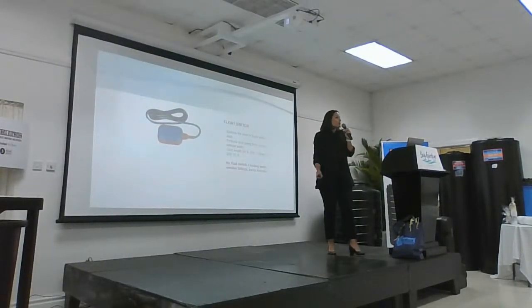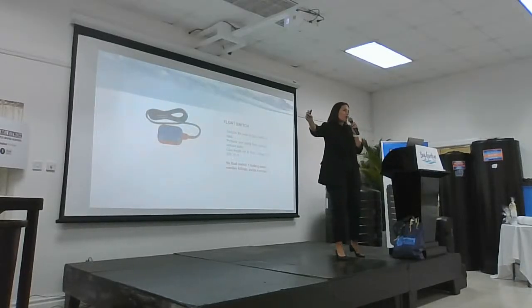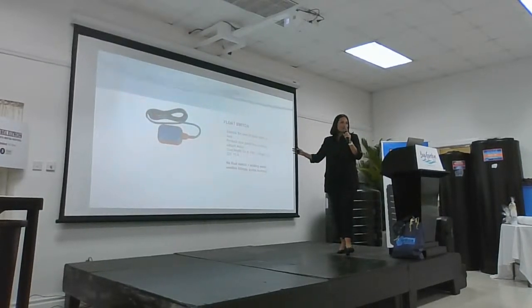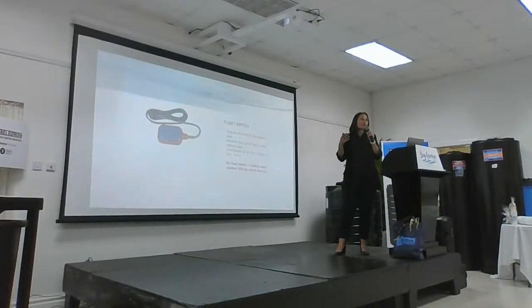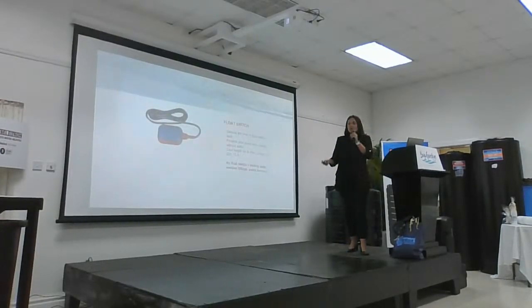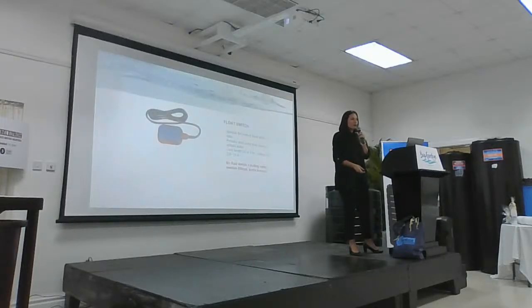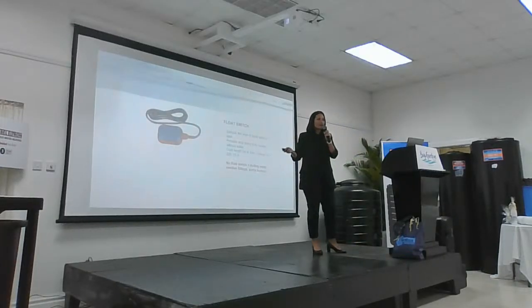The float switch is installed in your water tank and it's connected to your water pump. It prevents your pump from running without water, or dry run. Why this is important is that if your pump runs without water, it can have serious repercussions: boiling water from overheating, swollen fittings, and ultimately water pump burnout. A float switch is absolutely essential to installing any pressure tank system. This is what you need for the warranty for your pump. Otherwise, any dry run operation will not be covered under warranty.